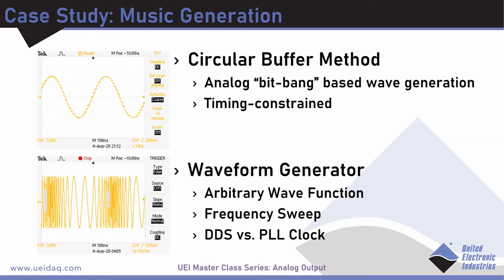The idea is that you can provide a certain register with several values. You can preload a register with several values that the waveform generator can output consecutively. And this makes generating, for example, those riffs that I spoke about earlier, much easier because you've preloaded them, and you can have the waveform generator handle the exact details of outputting them at the right timing schemes.